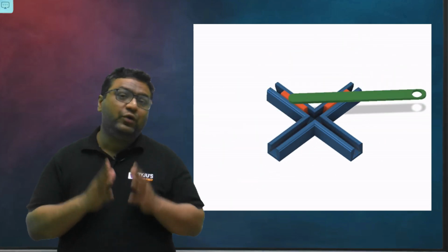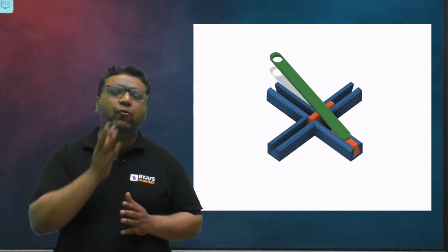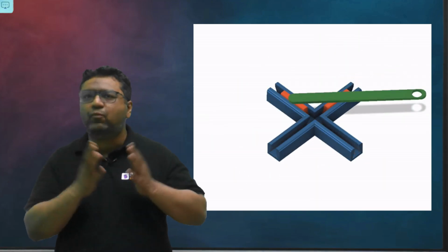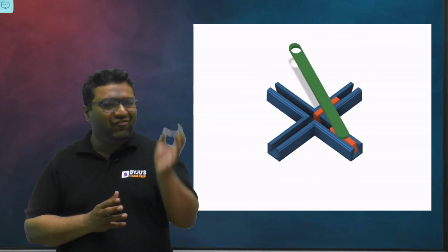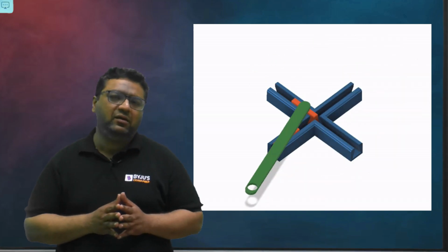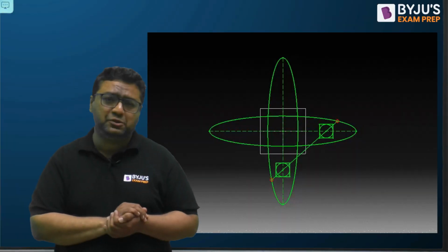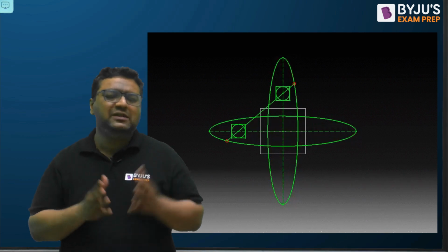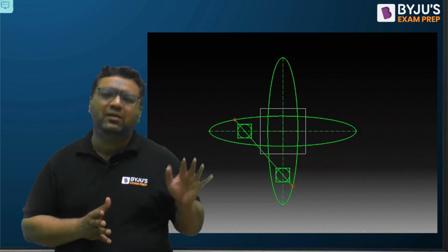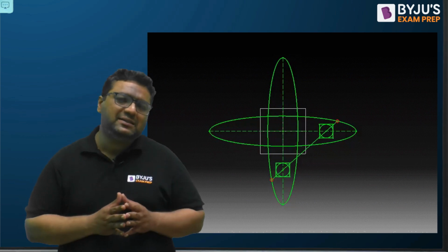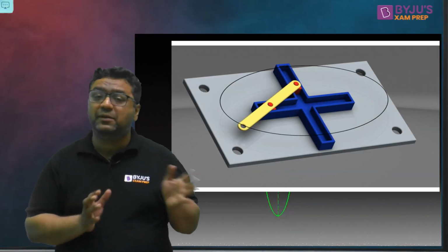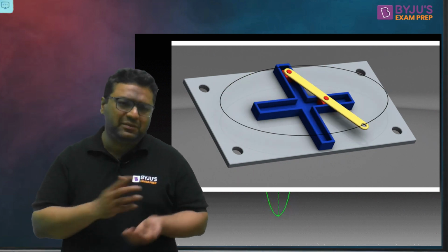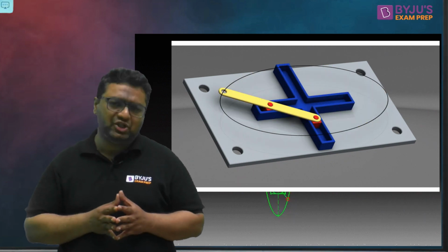Yes, if we keep the pen or pencil at the midpoint, you will get a circle. But for the infinite points present on a coupler, if we get a circle for one point, for other points we get an ellipse. So in general, we give the name ellipse, and that's why we say it is the elliptical trammel. This is the first inversion of the double slider mechanism, used to plot ellipses, majorly in civil engineering applications.